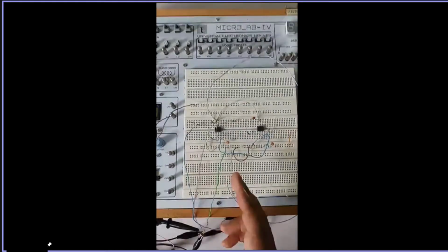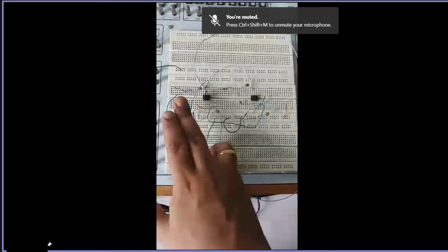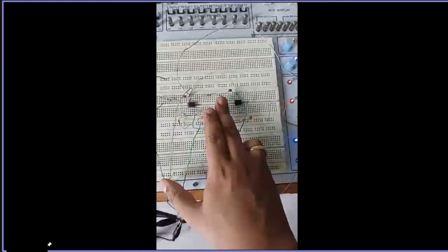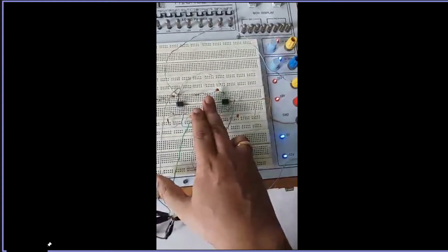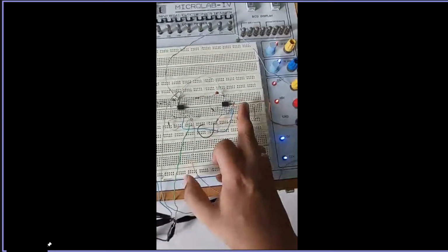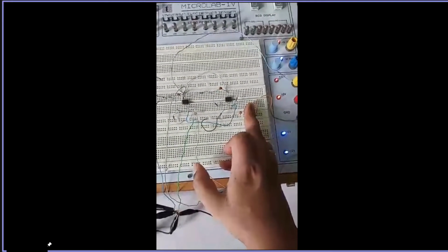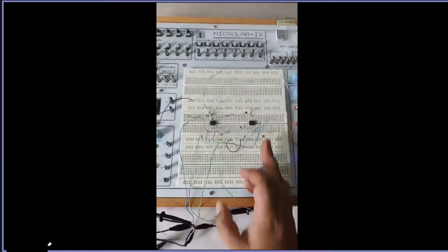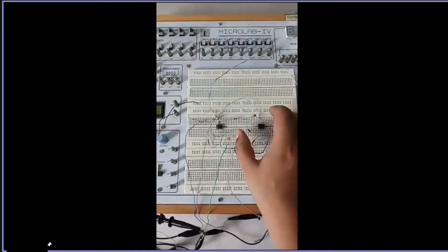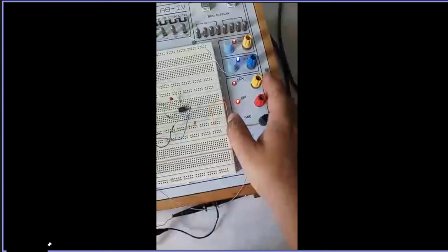So first of all, we'll try to take the input signal, then we'll get the output of the second order Butterworth, which will be input for the next layer, okay? And the output of this one will give you the output of the fourth order Butterworth low pass filter. Okay, so we have the structure. Actually, we have provided from here. This is the input section. The second order is this one, and fourth order is this one, and we will collect the output from here actually, because we are providing input from here.